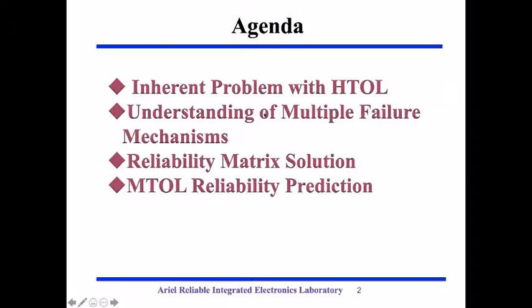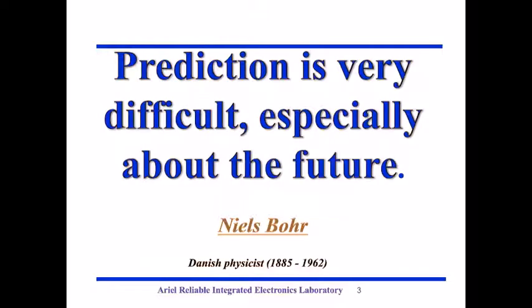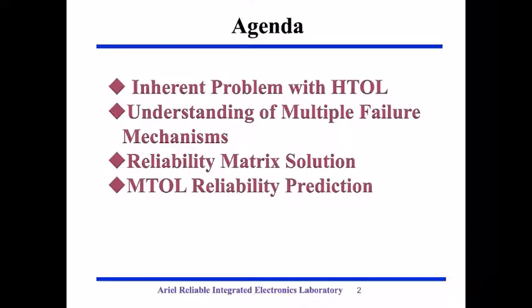There are inherent problems with HTOL, and I'll bring those up. The high temperature operating lifetime test, which is the industry standard, is basically a pretty useless exercise. We're going to understand what happens when you have interactions of multiple failure mechanisms at the same time in any system, certainly in any electronic product, any chip even, or MEMS systems, or LEDs, or anything else. And I'm going to present to you this reliability matrix solution that we perform for you, and we do this as a service.